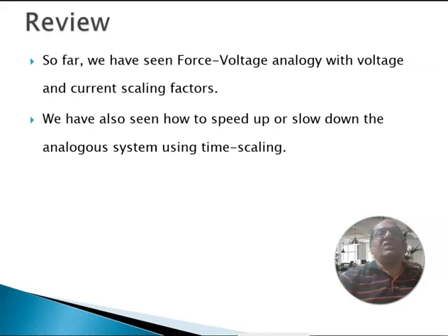We have also seen that we can adjust the time scaling so that events in mechanical systems occur either at a faster rate or slower rate. We call it time scaling. This force voltage analogy is also called direct analogy.